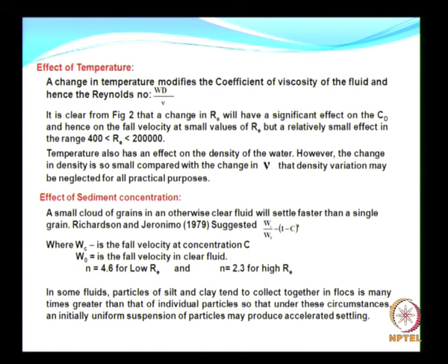In some fluids, particles of silt and clay tend to gather in flocs many times greater than individual particles, so that under such circumstances an initially uniform suspension may produce accelerated settling.